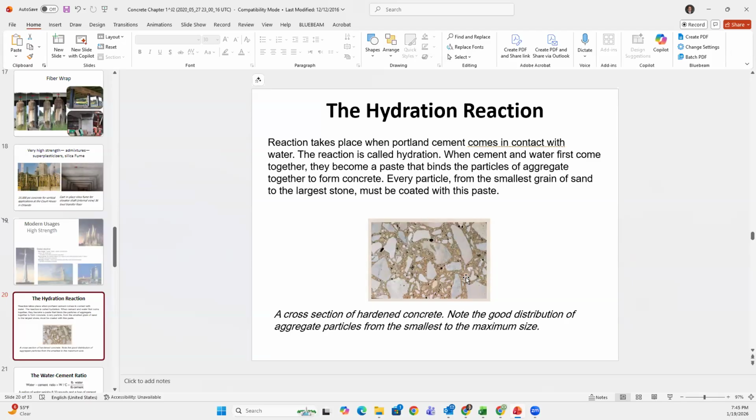I'm sure you have seen them. Are those rocks good for concrete? No. You don't want a river rock. You don't want a rock that has hit other rocks and become smooth. You want jagged aggregate that has a lot of corners and shapes, so it can glue and connect better. Smooth rock slips off. You don't want smoothness.